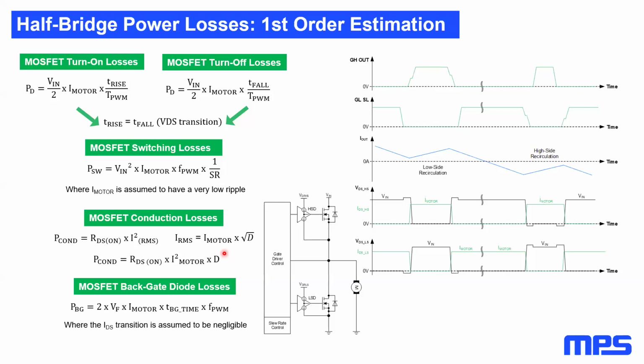The self-heating in the aluminum capacitor can be quite significant, with implications on the lifetime and reliability of the capacitor. So a very important point, very good question.